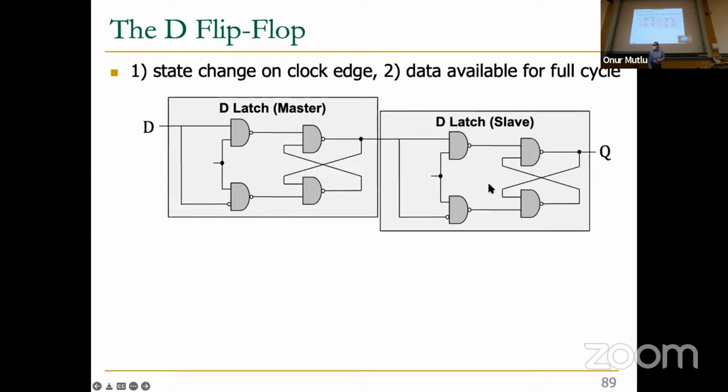Now it's becoming costly, right? So why is it going to be this way? Well, you will see the operation. Then we're going to wire the clock over here. When the clock is 1 over here, this is the write enable, remember? When the clock is 1 over here, Q gets whatever value is over here. But when the clock is 1 over here, the clock is 0 over here, so this value doesn't change. Now this is interesting, right? Basically, you're having this control.